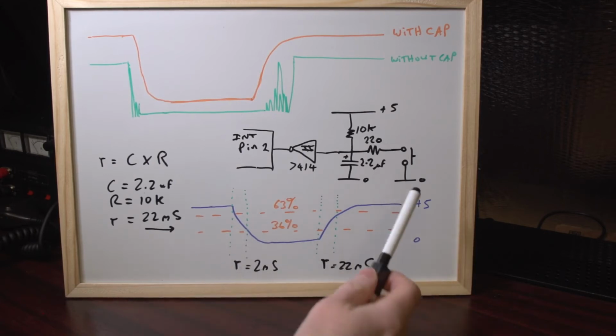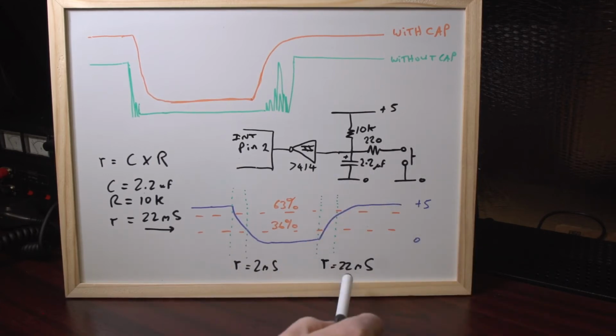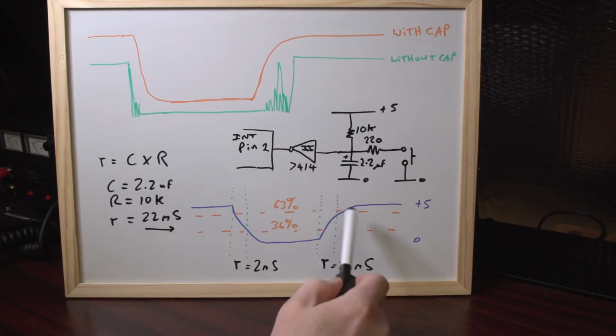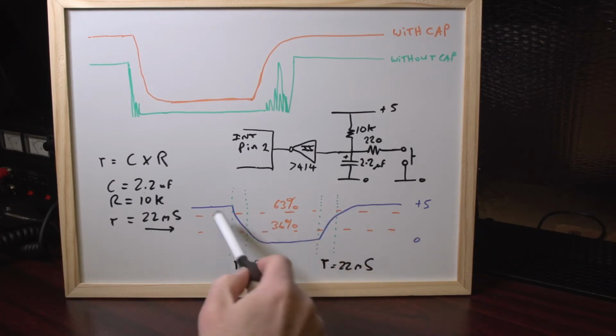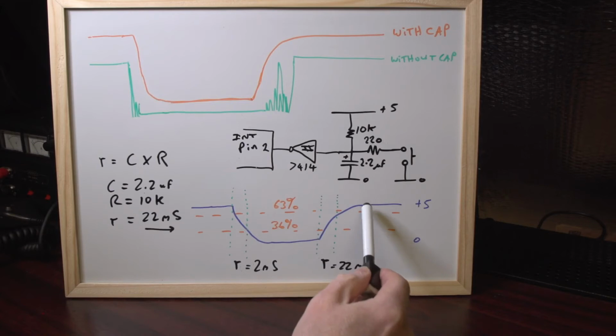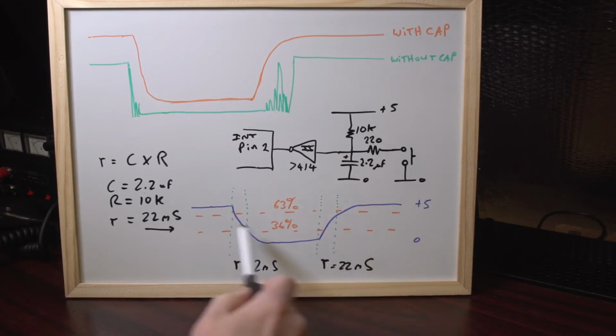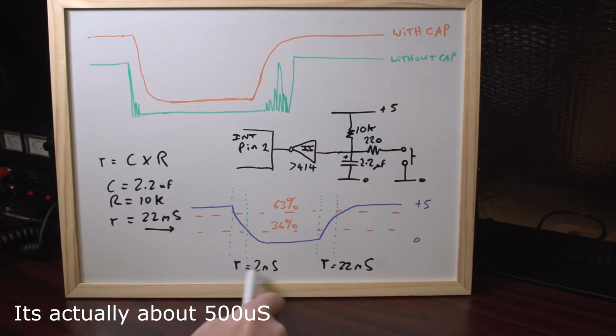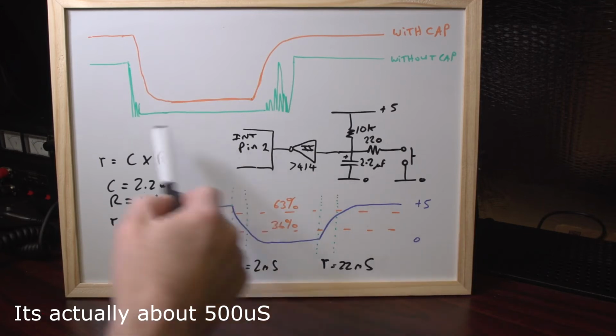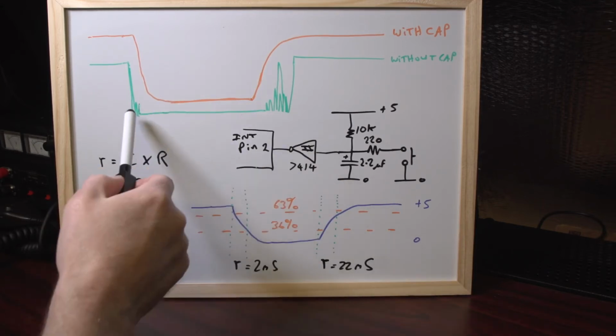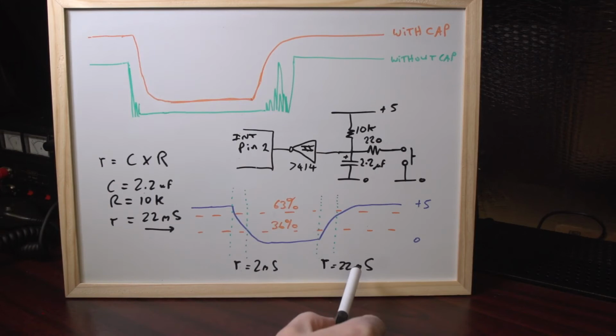And what you actually end up with because of these component values, you end up with something like 22 milliseconds on the release edge. That's the rising edge, and that's the falling edge. You get about 22 milliseconds there. And on the falling edge, we'll get something like about 2 milliseconds or less than that actually. Probably 1.5, something like that. So that actually smoothed out the leading edge and the falling edge noise. That's going to be perfect.